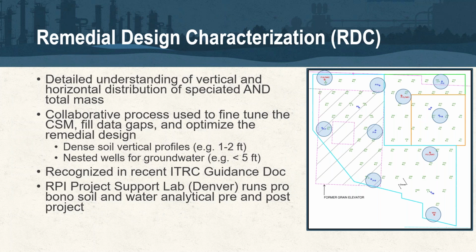It's a collaborative process where we work with our clients and consultants to review the current CSM and see if we can leverage the laboratory to fill some of those data gaps and really fine tune the CSM. Just to give you some general terms, in general, we're profiling soil every 1 to 2 feet vertically down through the saturated zone.